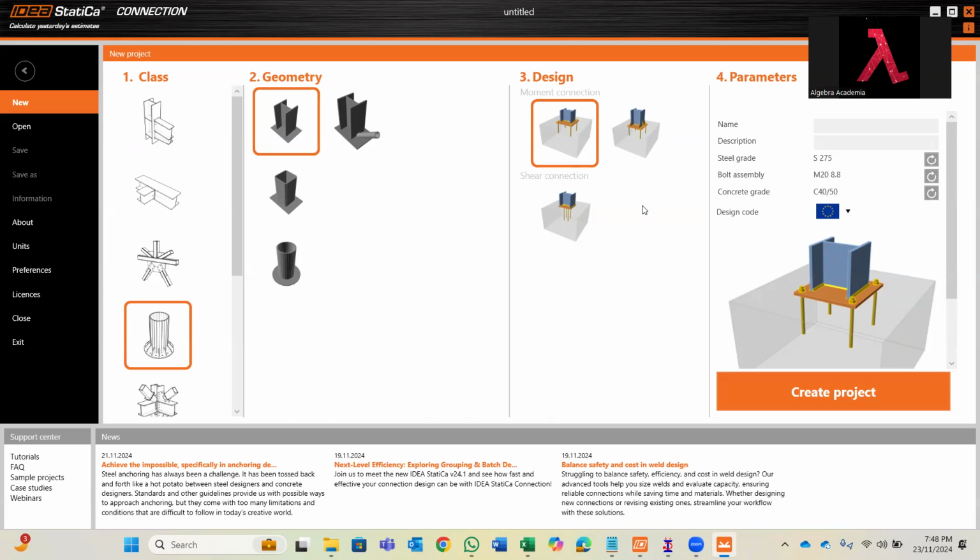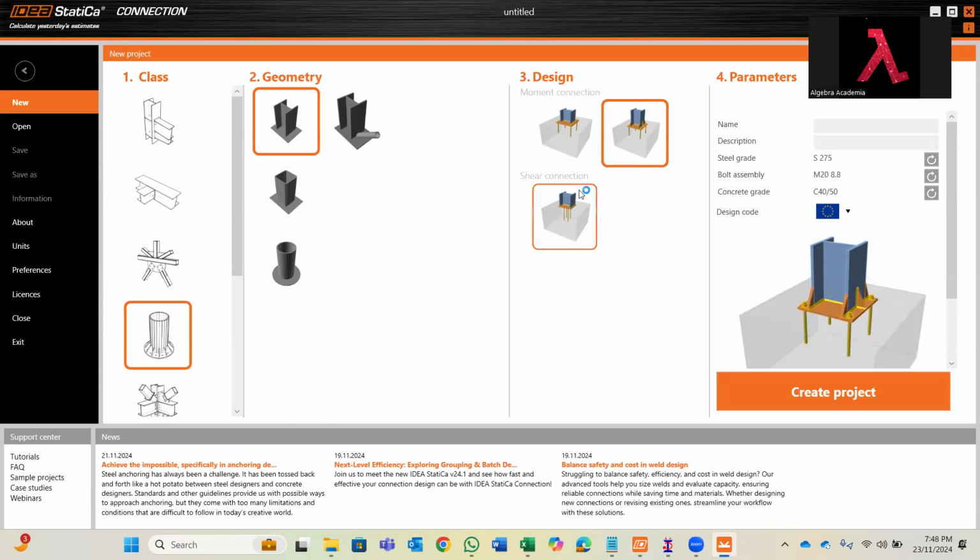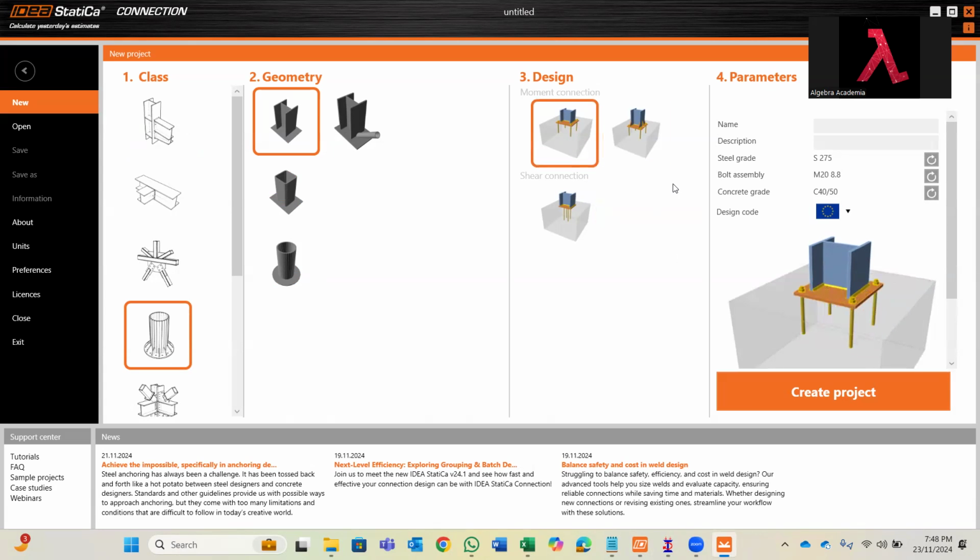If you go for the third sections, it defines where you do have a stiffener plate, where it's a pinned connection. Can you see here the bolt which is inside the section sizes? The first one is a fixed connection, because the bolt is away from the section. The steel grade is S275 and bolt M20, which we can change. Even while going inside, this is all just a template. So what I'm trying to say, we can just choose a template, and whatever the section sizes, bolt diameters and base plate dimensions, everything you can change, even including the code as well. So let's go for create project.